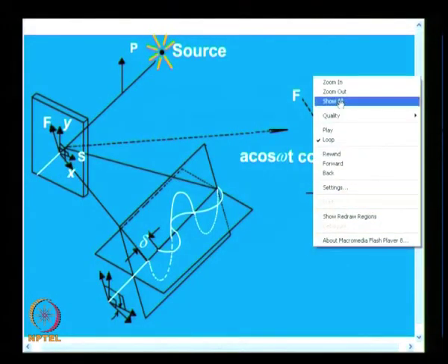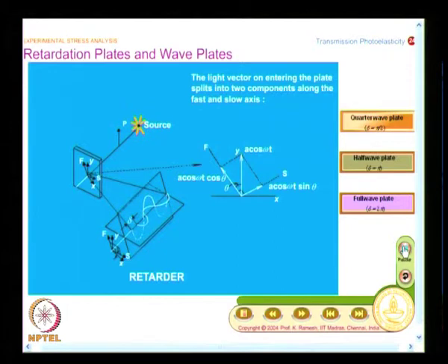If I have two simple harmonic motions which are mutually perpendicular, and they have a phase difference, depending on the difference in phase, you will see lights of different states of polarization, and let us see that. So, I will have a light ellipse coming out of the model. I use model and crystal plate interchangeably, please pardon me, and a model behaves like a crystal plate when stressed. In a crystal plate, it is naturally having birefringence, that is the only difference.